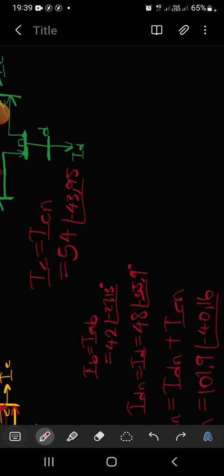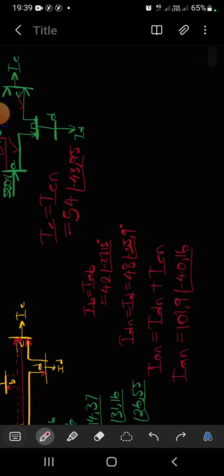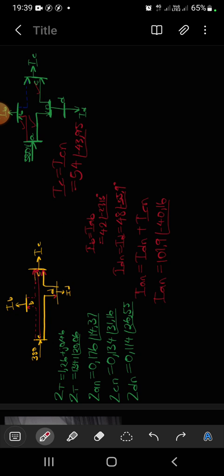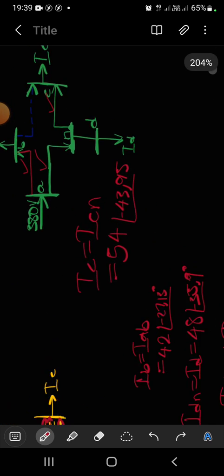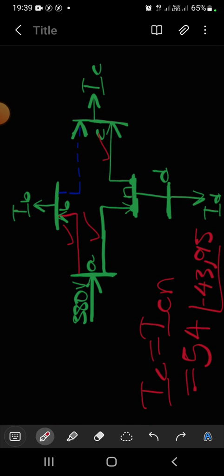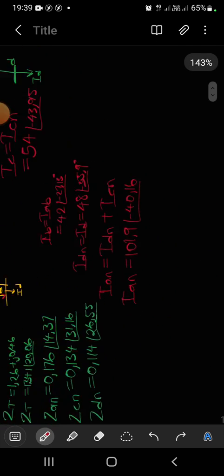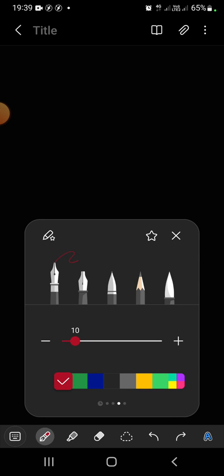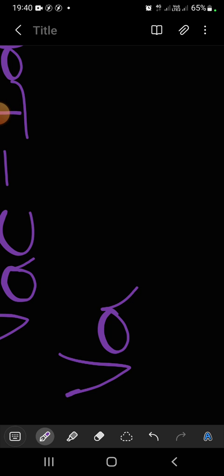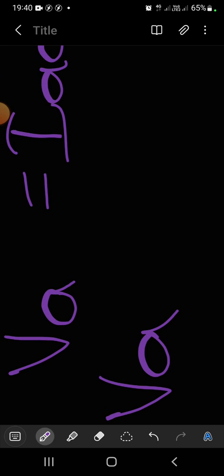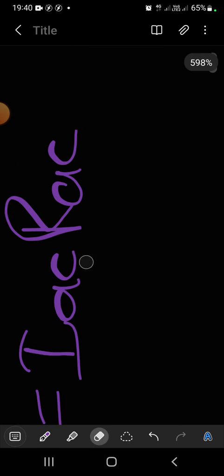Now our next step is to find the voltages. I hope you are aware that we're doing everything that we did with the AC ring. Right after having this circuit, we're repeating the same thing. We took advantage of the series current, and now we have to find the voltage of each section, meaning we are now looking for VAC, which is going to be IAC times RAC. You agreeing? And then we're also going to look for VAB. I'm sorry, it's AB because the section BC has been removed.